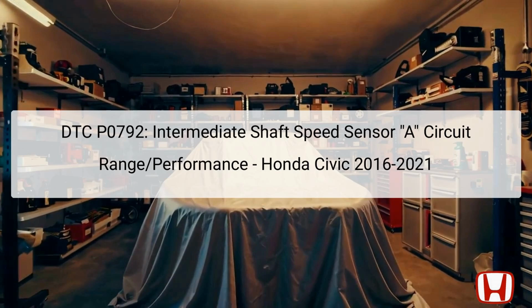The diagnostic trouble code P0792 relates to the intermediate shaft speed sensor A circuit performance in 2016 to 2021 Honda Civic models. This specific error indicates that the CVT, continuously variable transmission, drive pulley speed sensor is not functioning properly. The sensor is crucial as it monitors the speed of the gear on the drive pulley and communicates this information to the Transmission Control Module, TCM, by sending a pulsing signal. This feedback allows the TCM to manage the functioning of the CVT effectively.